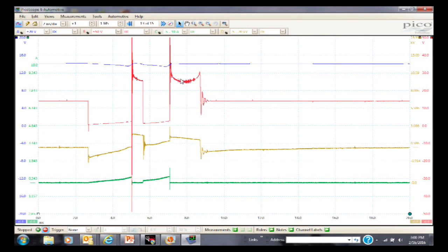We're looking for turbulence, a lot of turbulence. This is a modest amount of turbulence. If we see the pattern jump up significantly towards the end of the burn, that's representing that we're running out of fuel at the time. And if it stays fairly steady or has a little bit of a bell curve like that, fairly normal. Again, you want to check as many cars as you can so you have a nice little pattern library going.